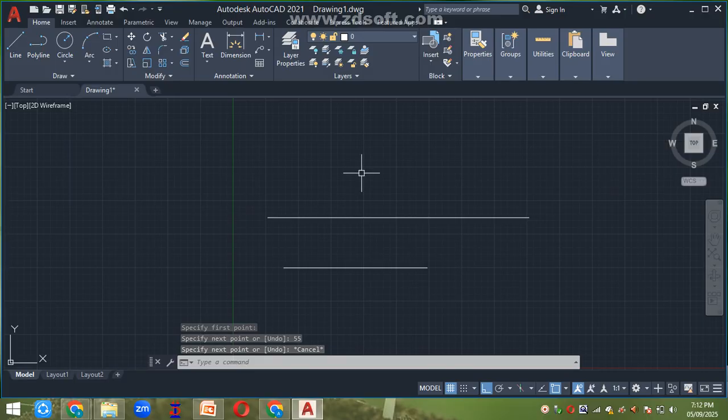Now once again I will draw a vertical line. I will specify the first point. Now the span is 29 meters, enter, escape. Now I am supposed to measure this. How to measure this? Since the horizontal and vertical lines I have drawn are of linear dimension.